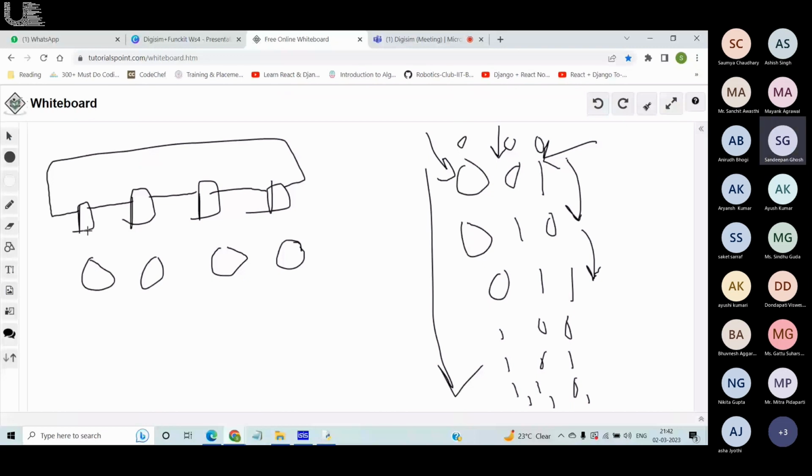If you remember, in the last workshop we taught you that there are two extra pins to the flip flop. One is set, one is reset. So let this be the set pin. If I drive this pin, then my output becomes 1. If I'm giving 5 volts to this pin, my output becomes 1 here, of the flip flop. So imagine I'm giving a short pulse and I drive the output to 1. So I'm having 1 0 0 0, externally.